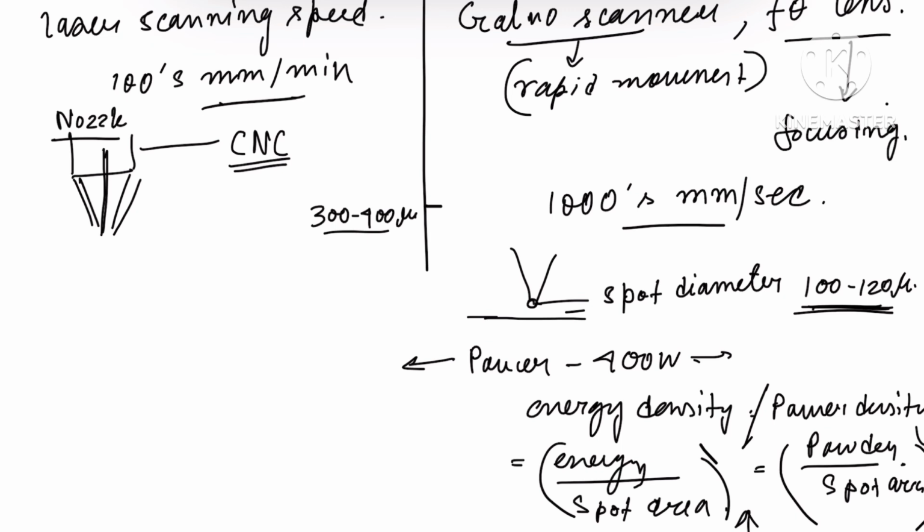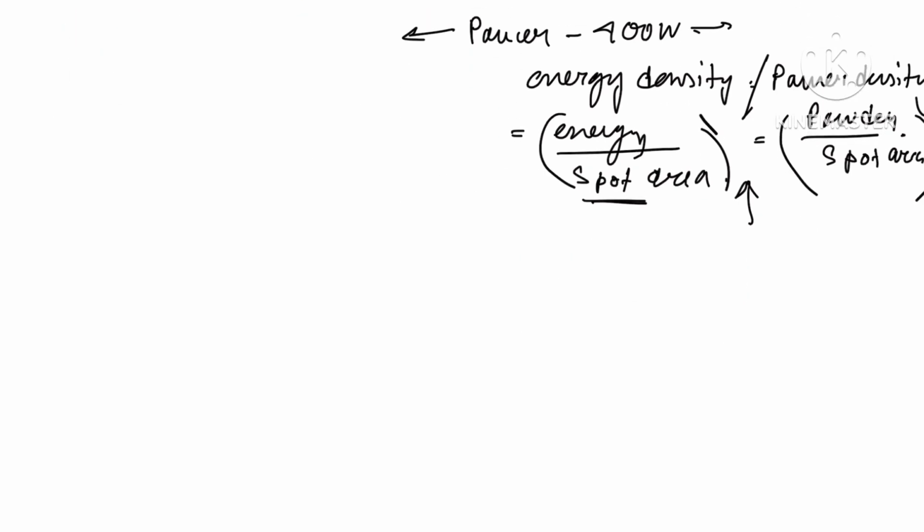So this high energy density can cut through the build plate if the speed is lower. Our motive is to melt a very thin layer of powder over this powder bed, which layer will also have a thickness of 20 to 40 micrometer. So to melt this thin layer over the powder bed, the laser's focus spot needs to move rapidly. Otherwise, it will cut through the build plate. So this is why in the case of LPBF, the speed is really high and this high speed is needed.